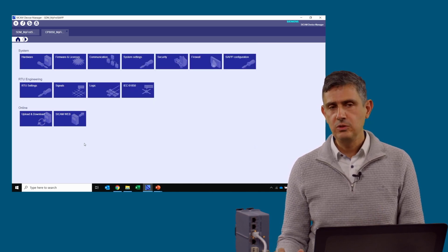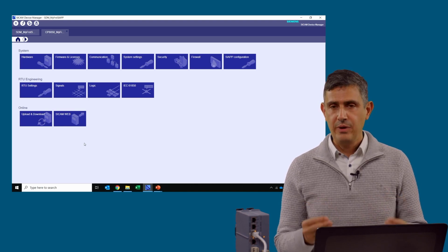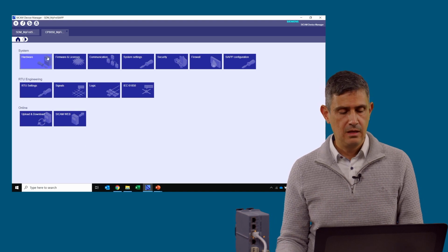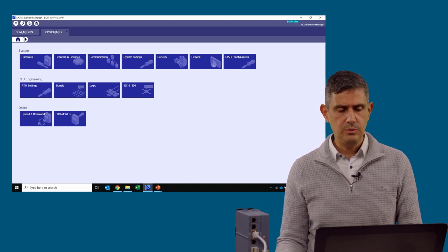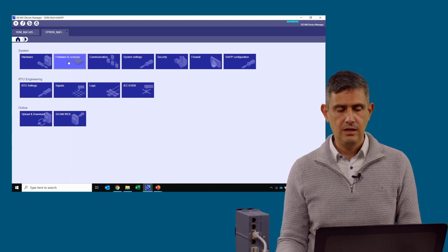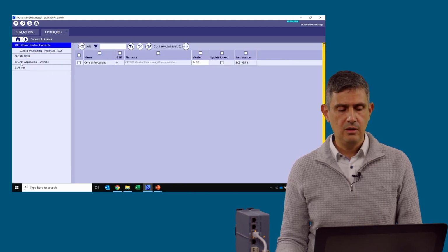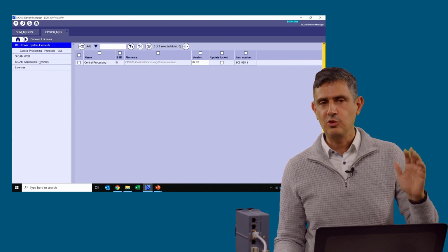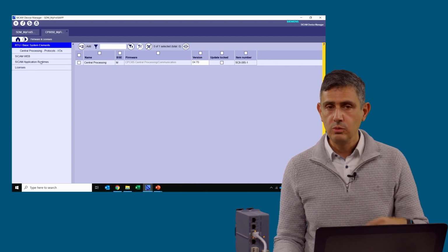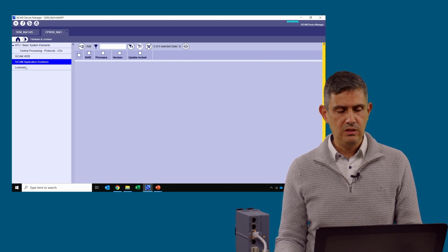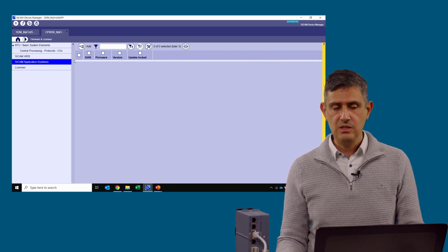First thing that we will do in this case is we will prepare the RTU to work with the SIAPP. So we will go in the CP8050, where we have here firmware and licenses, and we will go to SICAM Application Runtimes. By the way, this is SICAM Device Manager, of course, the software that is used to configure the RTUs to be able to load also the SIAPPs there. So we go here in firmware to SICAM Application Runtimes, and we will add